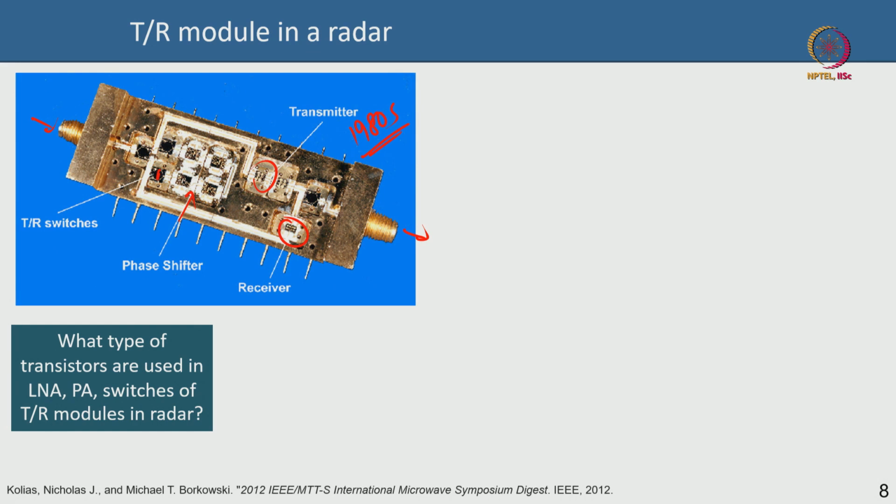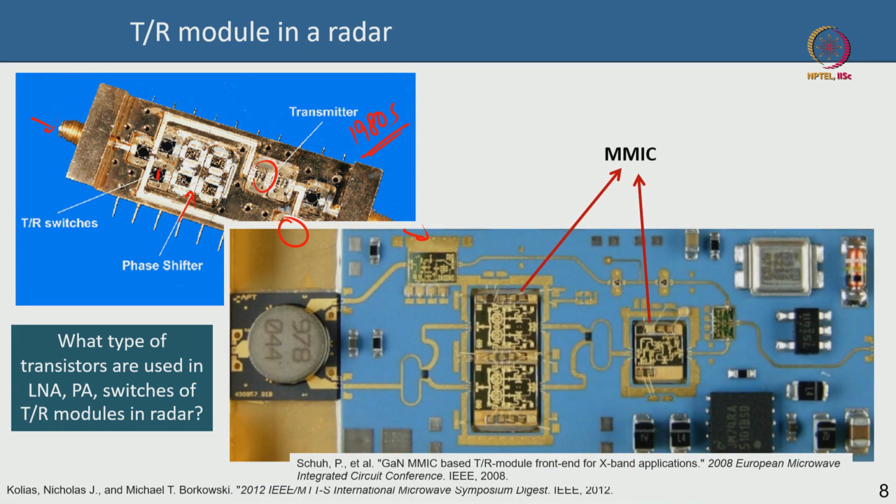In more recent technologies people use something called MMIC. I already have used this term probably. MMIC stands for monolithic microwave integrated circuit. Microwave because it's an RF signal. Monolithic means it's fabricated on the same die, the same semiconductor wafer. You fabricate everything: all the passives, capacitors, inductors, transmission lines, switches, active devices like amplifiers, low noise amplifier, power amplifier, power splitter, power combiner, circulators, couplers. All these things you might want to implement on the same semiconductor wafer. It's called monolithic, same piece.